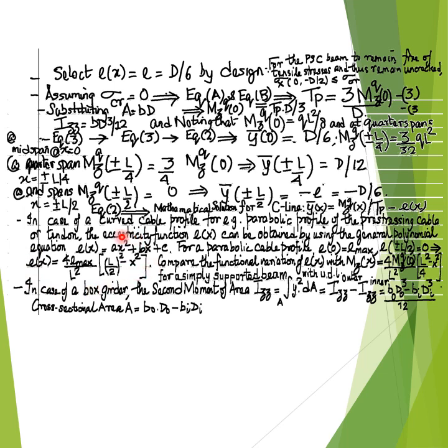should also be examined to verify that the cable profile depicted by the eccentricity function e with the argument x resembles the shape of the bending moment diagram due to the externally applied uniformly distributed load.